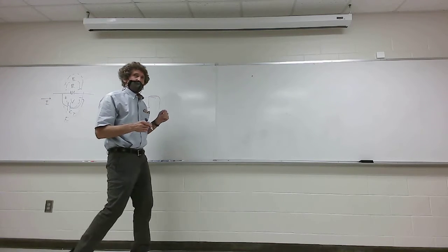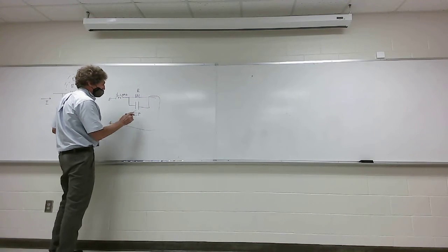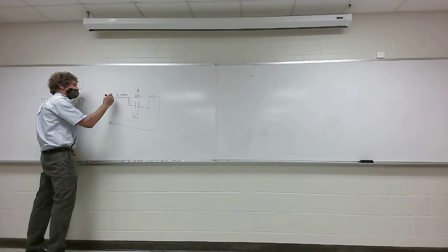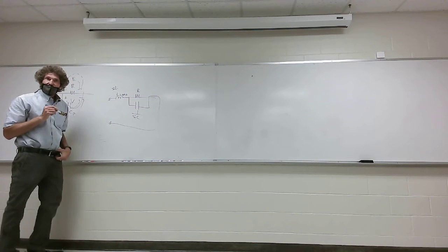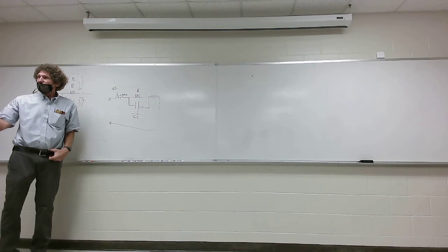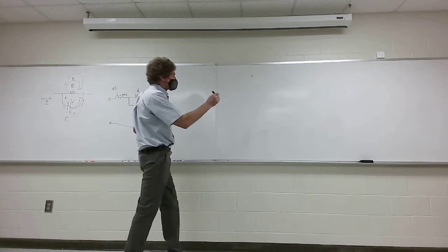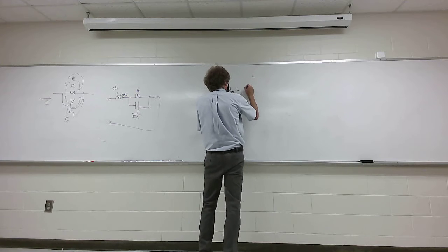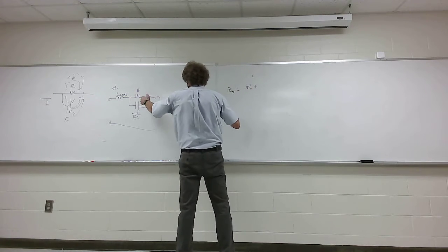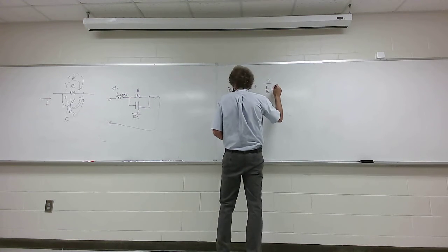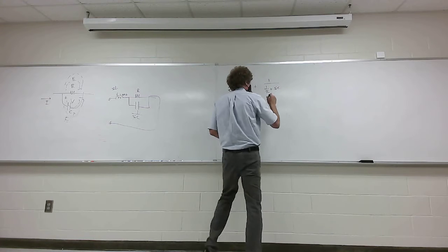All right, so how do we model this? There's a couple of ways. We know the impedance of this is 1 over SC, and the impedance of this is just S times L, isn't it, class? Are you familiar with SL? S is j omega, okay? If you think about that, what is the impedance of that? Well, it would be SL, right? Plus, these two are in parallel, right? So I can have 1 over R plus SC. Do you agree with that?